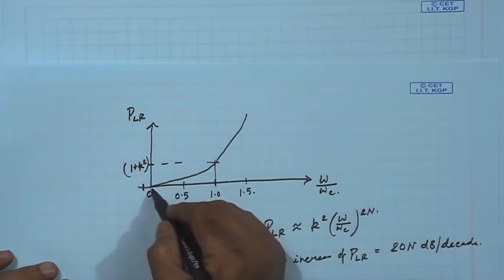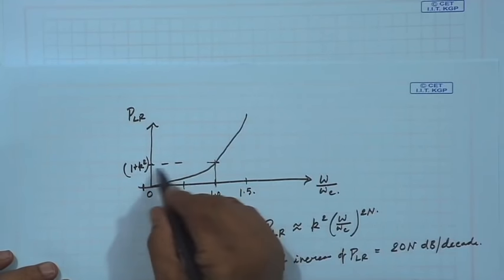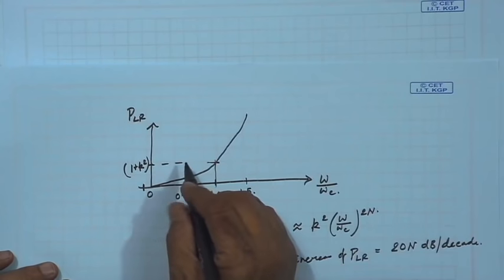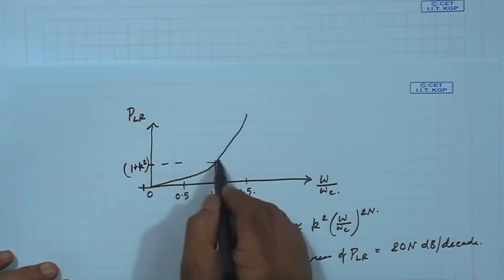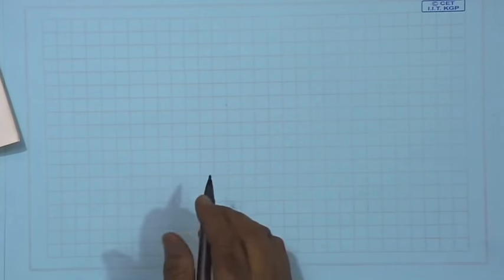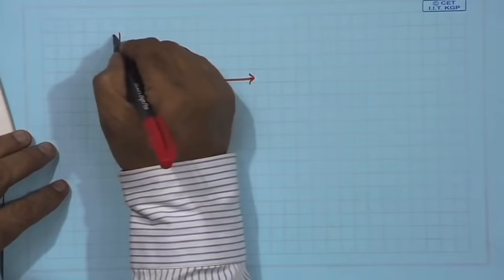I do not mind if, instead of monotonically increasing in the pass band, the insertion loss ripples, that means I can have high and low, but do not cross this limit. So, that is possible. Chebyshev is the sharpest one, or much sharper than our Butterworth.